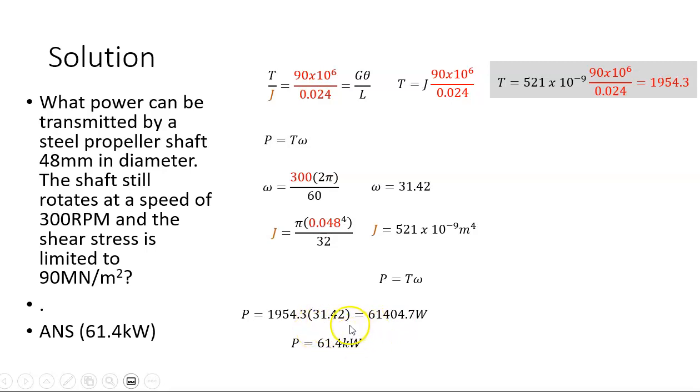So yeah, that confirms what we thought, that shaving 1 millimeter off the outside of the shaft has a lot more effect than taking 20 millimeters from the center of the shaft.